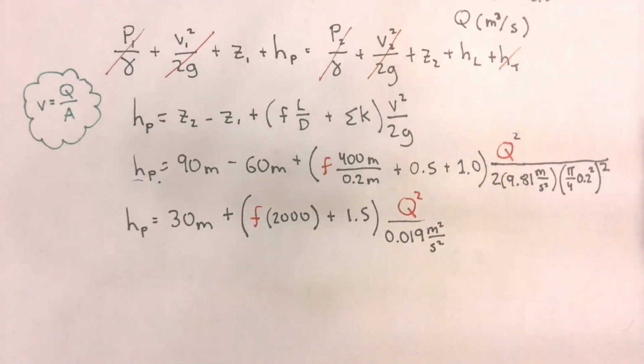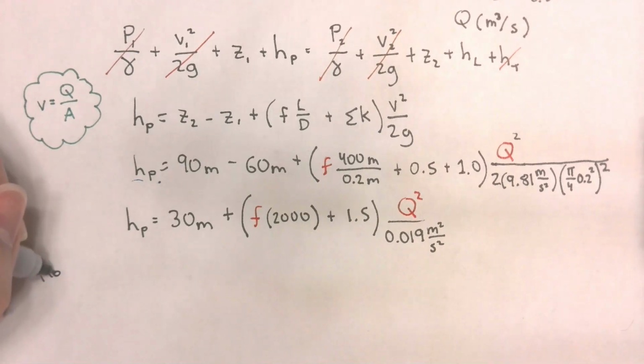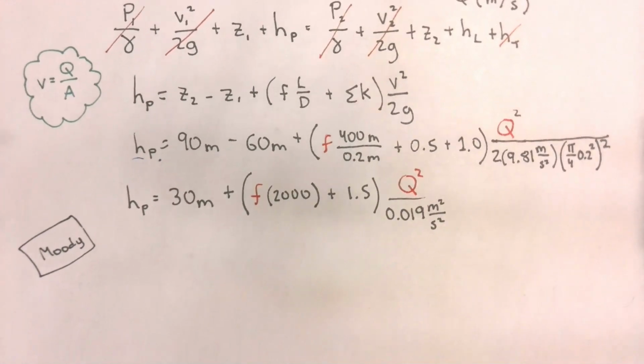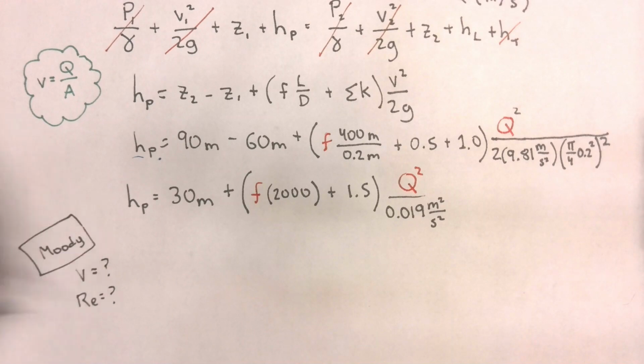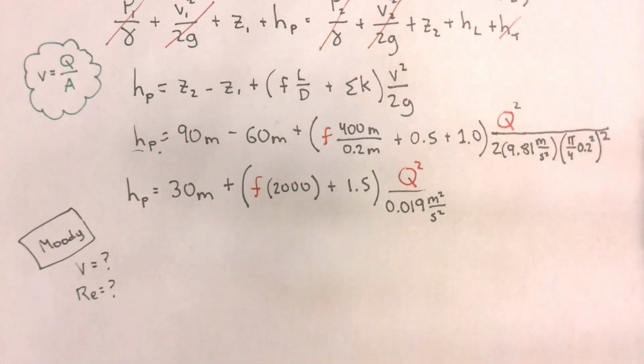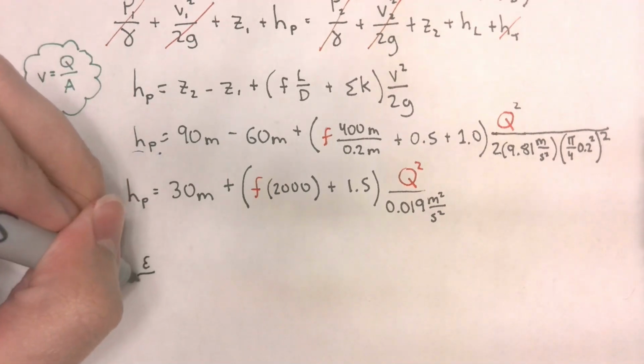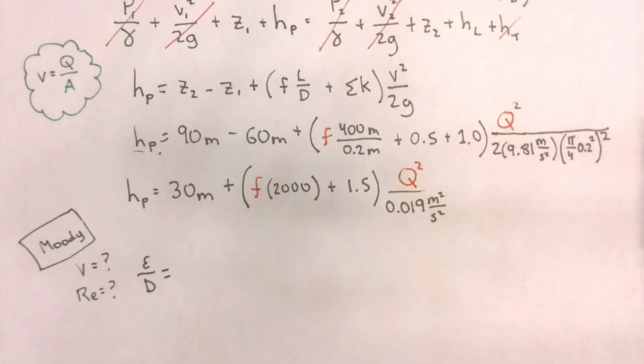So if I want to find the friction factor assuming fully turbulent flow, normally I would first find the velocity and the Reynolds number, but it's fully turbulent flow, so we don't need it. What's the other parameter that I need to find to use the Moody diagram? The roughness height. The relative roughness, right? Specifically the relative roughness. Good. We know that this is a wrought iron pipe.